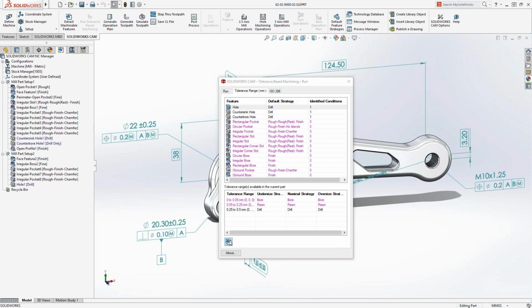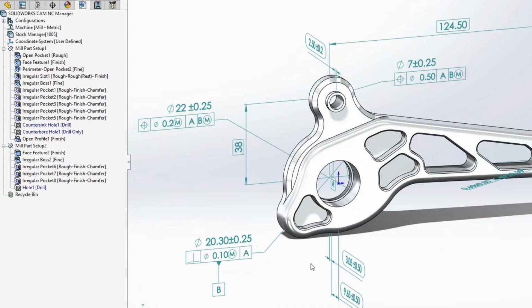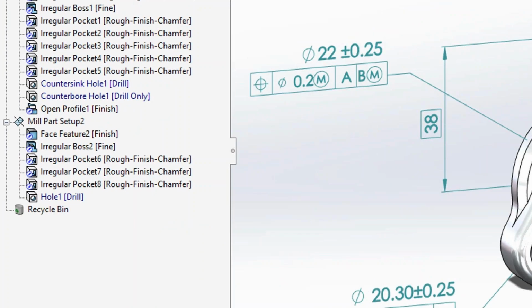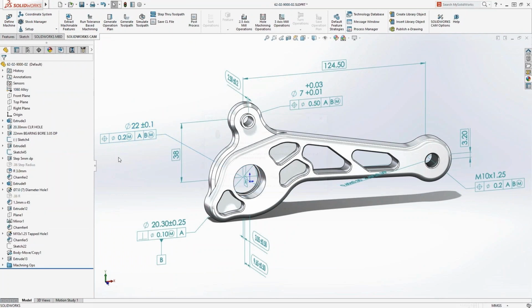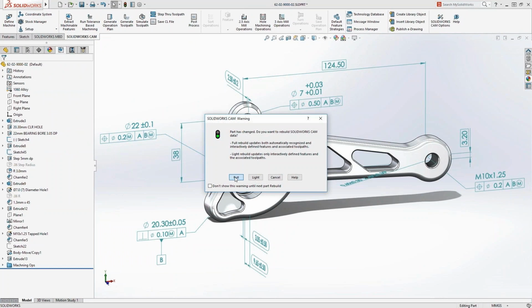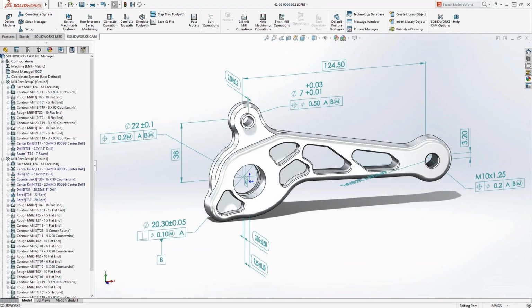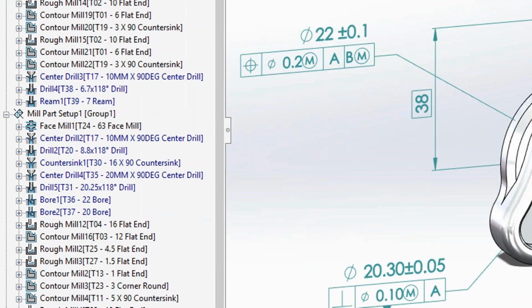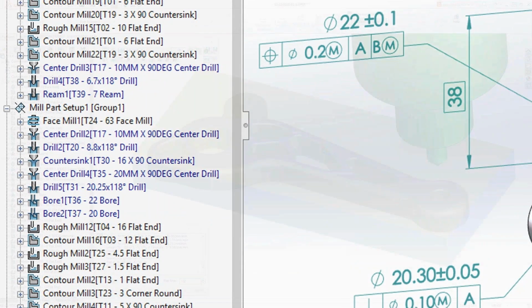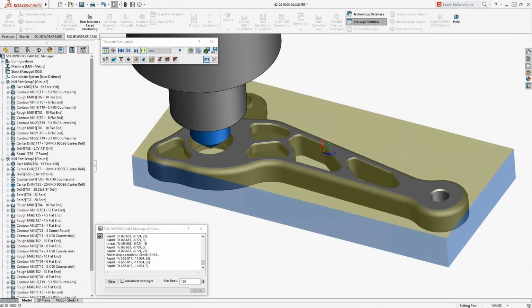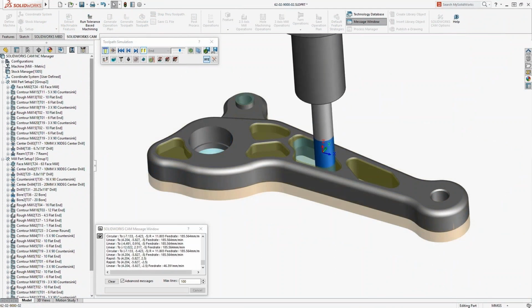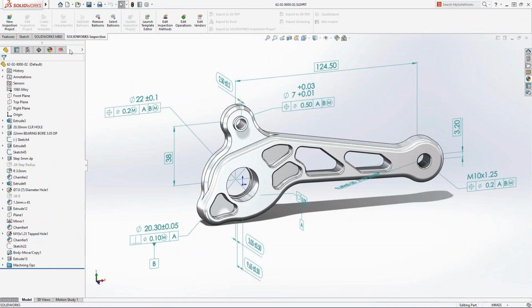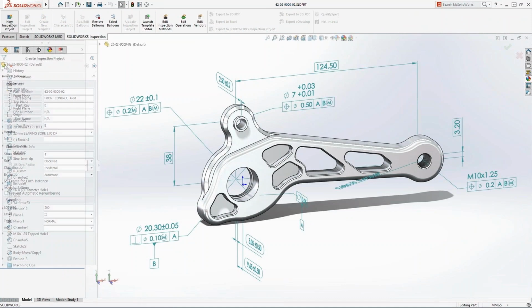Right? Now, you could take this model and go directly to SolidWorks CAM. SolidWorks CAM is rules-based machining. That means basically we can look at that model, we can recognize how it has to be machined, and there's a database that understands what kind of tool paths and what tools and what speeds and feeds I should be using to machine that model. So it really speeds up that whole process of developing tool paths.